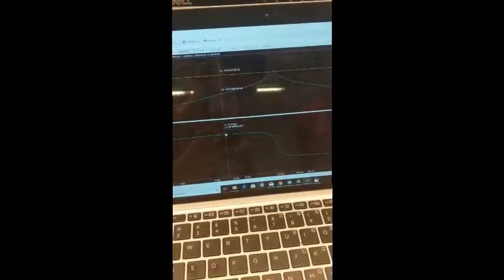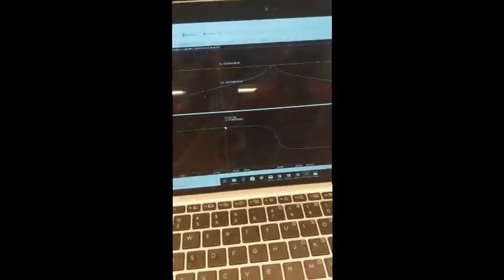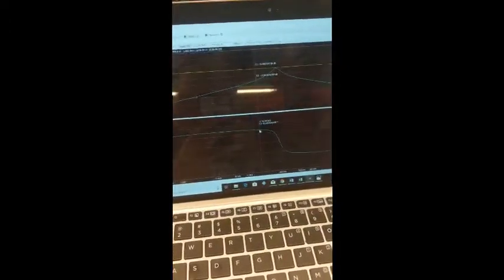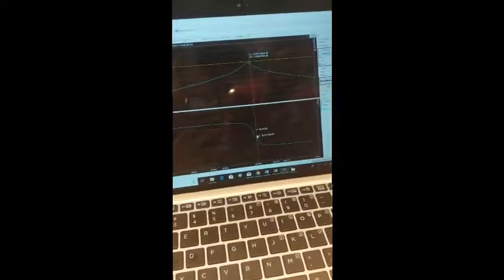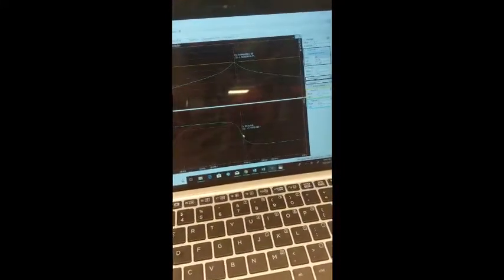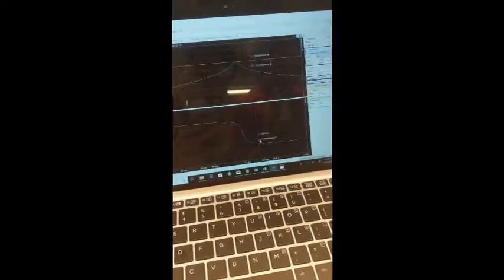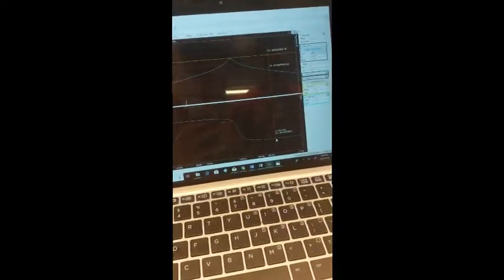The phase angle of the output signal leads that of the input by up to 90 degrees, right here, to the center resonance frequency, which is 0 here. It's in phase, and then it will change and lag the input to negative 90 here as the output frequency increases.